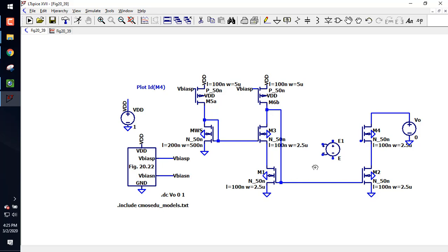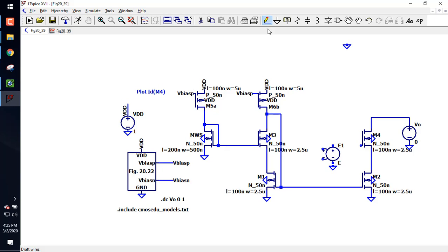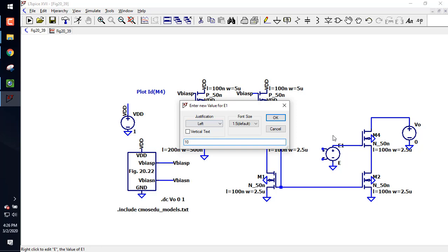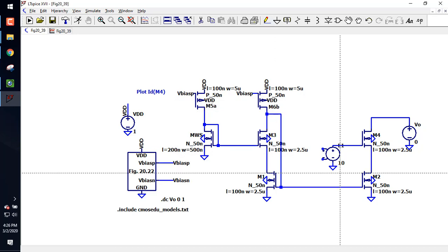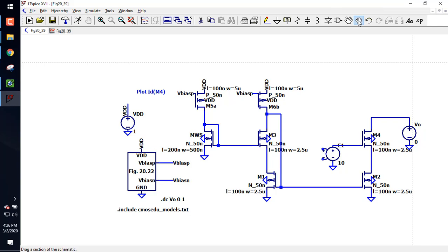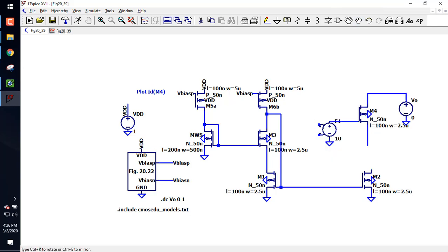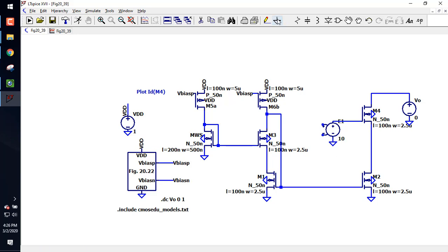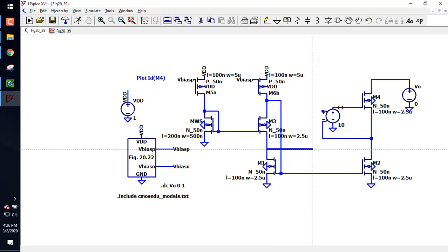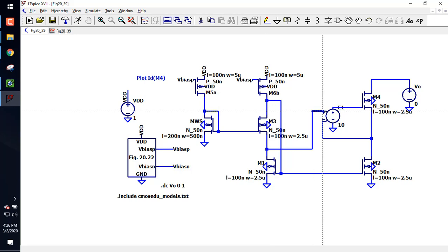All right. So press G and then wire it up. Let's give it a gain of, how about just 10? And then let's do our little negative feedback. Let's go here, here. And where do I connect this? On the left. Yeah, right over here, right? Because I want to regulate this voltage.